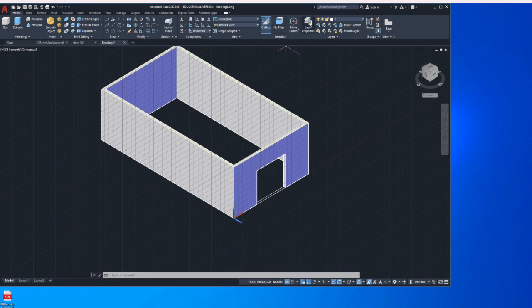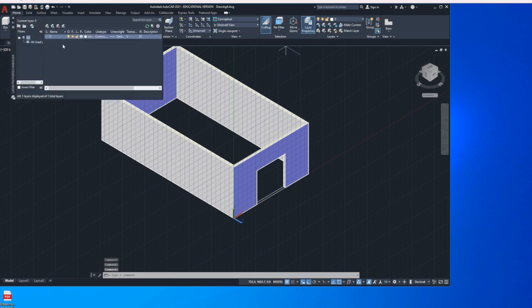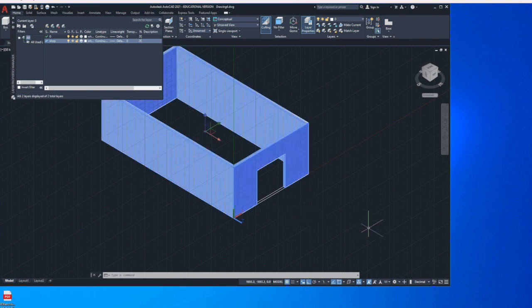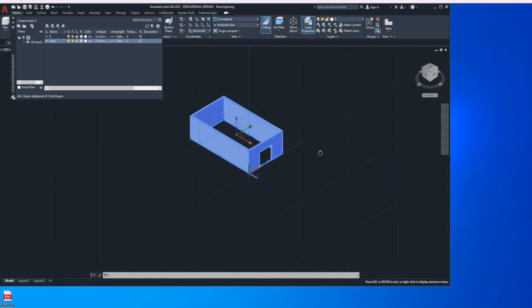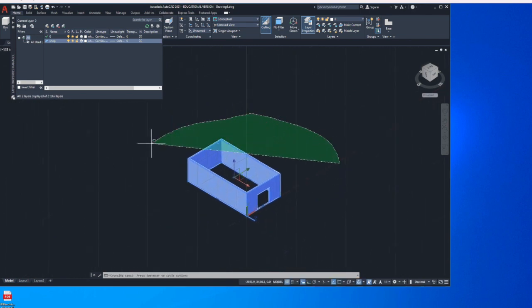So I'm going to come back up here and find the layers property and open it, and I'm going to tell it I want a new layer. I'm going to call the layer shop. Okay. So there's a layer shop, and I'm going to come down here, and I'm going to select everything that's in my drawing down here. Let me zoom out a little bit, and sometimes it's best to make a counterclockwise circle around it and make sure you got everything.